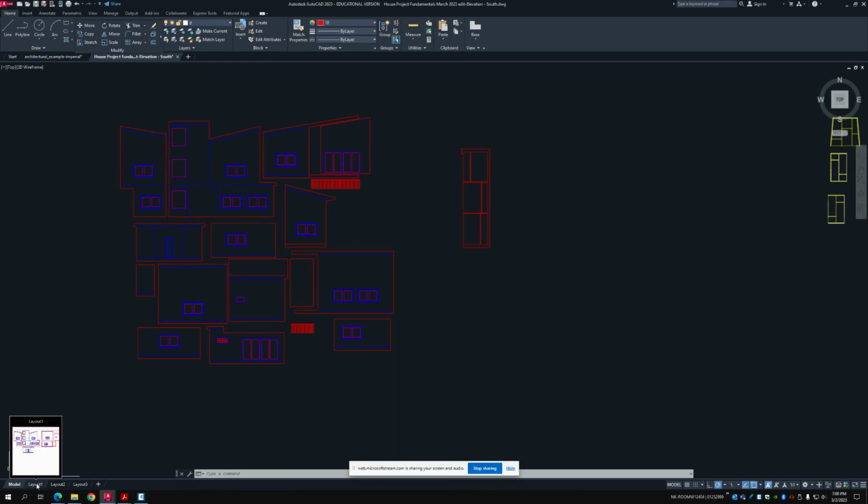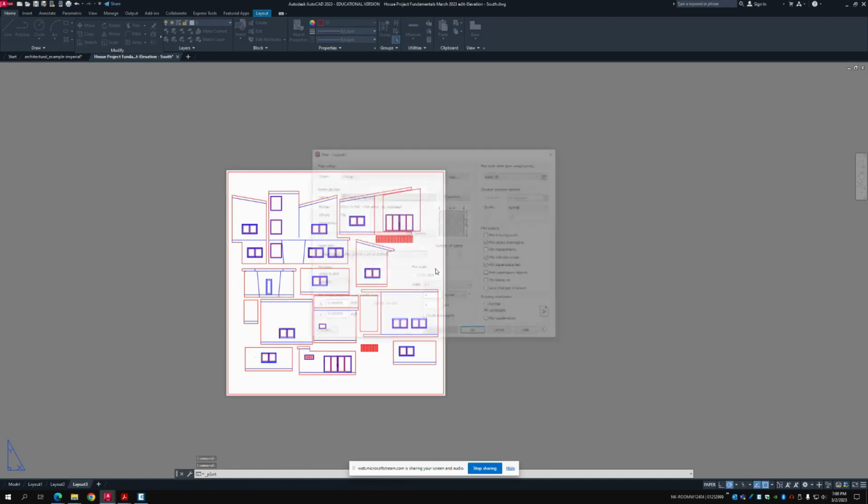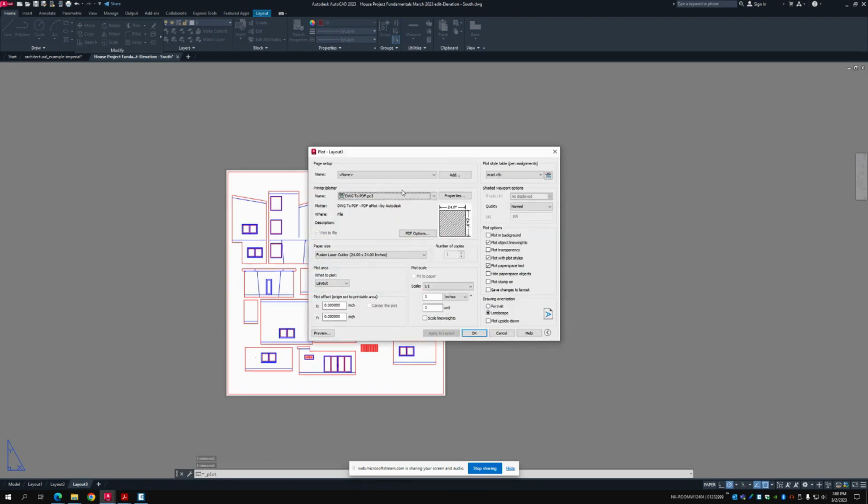So I'll show you a finalized drawing DWG file where everything was fit inside this 24-inch by 24-inch. Once that is finished and it's all nested together, you're saving your media space. You can go ahead and hit Control-P, continue to plot to a single page, and make sure that ACAD is selected.